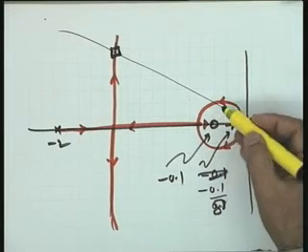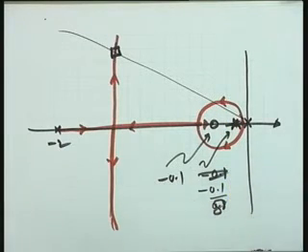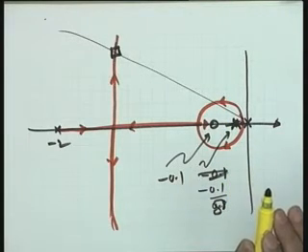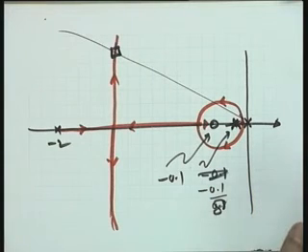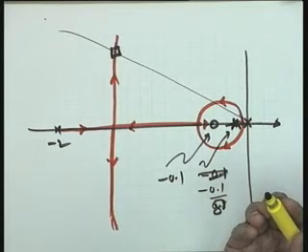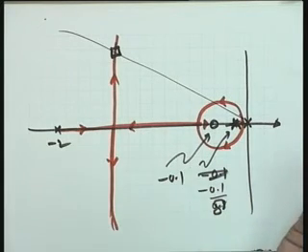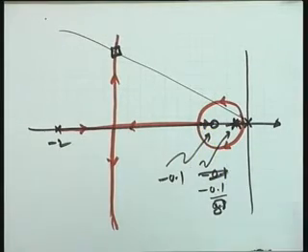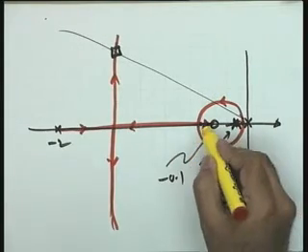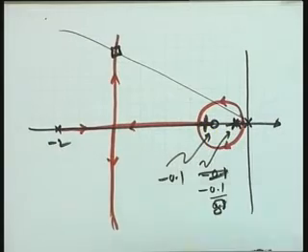Can you tell me, can the third pole be a complex pole? You see, all the poles have always to be complex conjugate. So in this case it is a third order system. So the third pole cannot be a complex pole. It has to be a real pole only. So that real pole, as can be checked, will lie in this vicinity, in this particular region.